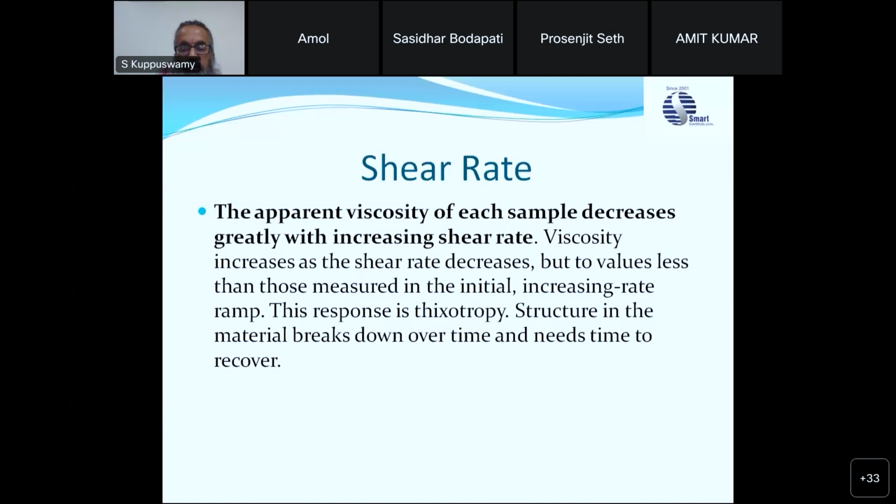In the viscometer, if they measure shear rate and shear stress, they are not analyzed with the regular spindles. They might be used with some coaxial cylinder geometry or the cone and plate geometry. If they mention a cylindrical spindle, that means it's a coaxial cylinder geometry with which they have generated the shear rate.